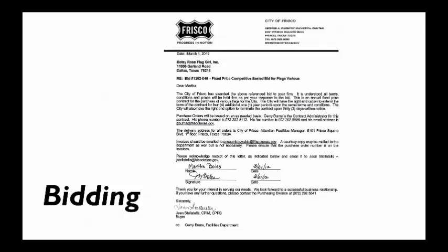Now, in a public project, a lot of times if you're using public funds, you might be required to use design, bid, build, because there may be some legal requirement that states that you're required as a city or county to accept the lowest bid so that you're using the least amount of money. Some other larger corporate or institutional clients might use the bid process, but that's essentially what we're talking about: bidding on the construction documents that are completed and making proposals on the contractor side for what could happen. And then the owner selects one from those bids.